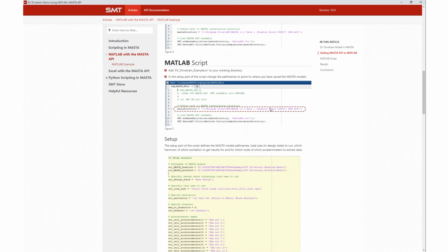So in terms of future work, we're working on a SolidWorks example. So now we have a .NET API. SolidWorks has a .NET API. We will be able to modify the FE from a scripted property in MASTA using the SolidWorks API. So we can do that from PST, use a scripted property in PST, parameterize the gear blank, parameterize radial holes, for example, in the gear blank, mesh it, import it into MASTA, and compare the gear whine results all automatically.